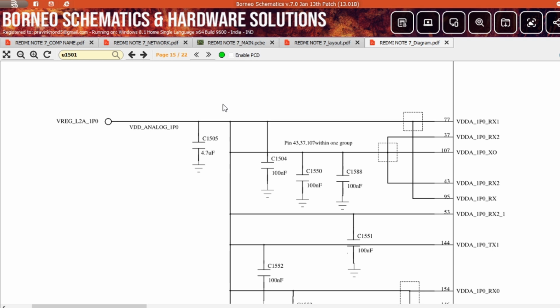Most common fault. When you check IMEI in dialer mode, you will see 00 or a question mark, right? When you go to the settings and check the baseband number, there is unknown. These are the common faults.